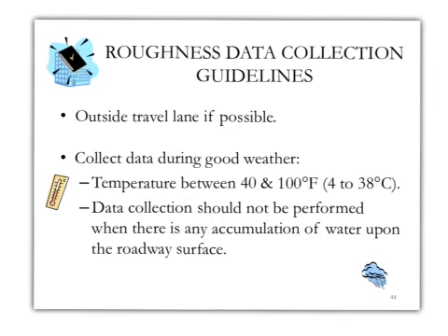For example, temperature has to be somewhere between 40 and 100. If you are really going on a snowy day, that's not the best day to do it. Or if it's at very high temperature, let's say 120 degrees in the middle of the summer in Phoenix, Arizona, that's also not a good selection, because now the binder may start to flow, and it's definitely going to change the roughness of the road on that day in particular.